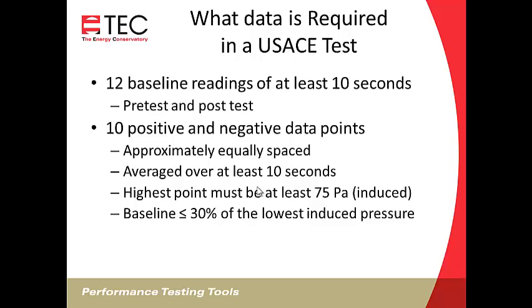It's less restrictive than ASTM E779, which has restrictions on temperature difference and height of the building and wind speed. This allows you to test under a lot more weather conditions than if you were strictly following ASTM E779.